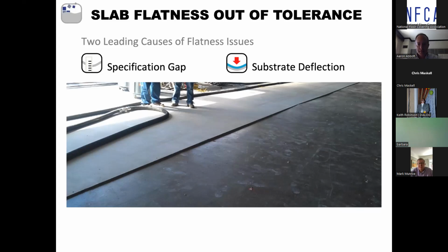So 500,000 square feet of parent concrete or base slab has to be poured and deliver 3/16 over 10 feet. I don't know how they're going to do it. And when the floor covering people show up later, there could be a lot of grinding then if there's no SLU involved, and it won't be in their price. Right. Who's responsible? It's going to be a very difficult scenario.